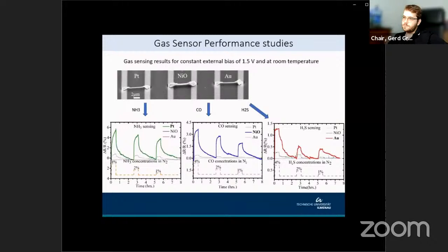Since we see that there is also an increase in resistance for other bridges, which means that there is a certain amount of cross sensitivity, what is possible is that we can extract the data out of these graphs and make use of neural networks or a pattern recognition software and follow the same principle which is for e-noses and use them to identify which gases are available in the environment.